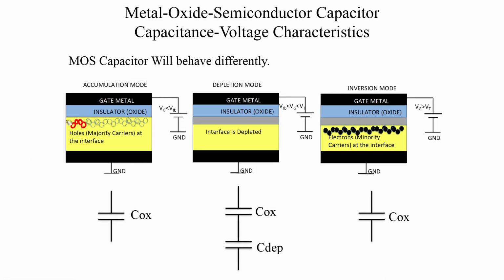So, for Vg less than Vfb, if I were to provide a small signal fluctuation, I have now set my gate DC voltage, right. So, let me pin my DC voltage first. We have now set Vg minus Vfb equal to minus 1 volt and left it there. Okay. So, our DC point is set, and now we are going to apply the small signal AC. Okay. So, I have forgotten to add the AC source everywhere.